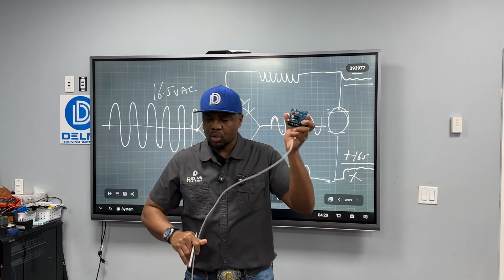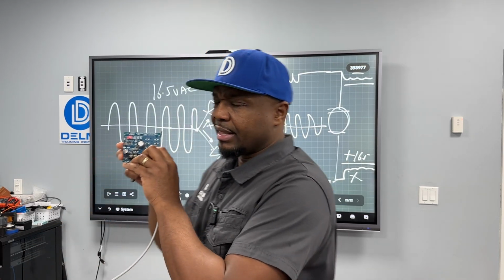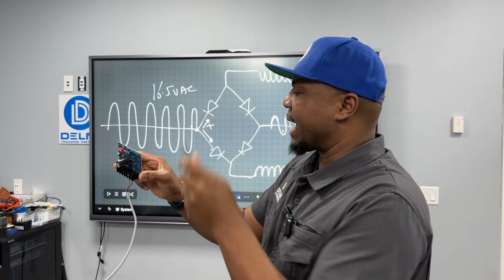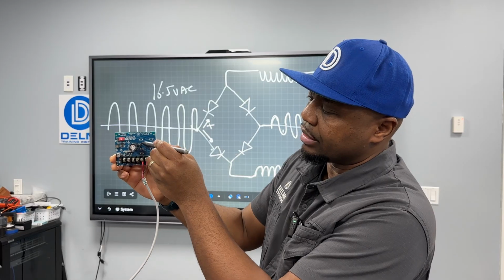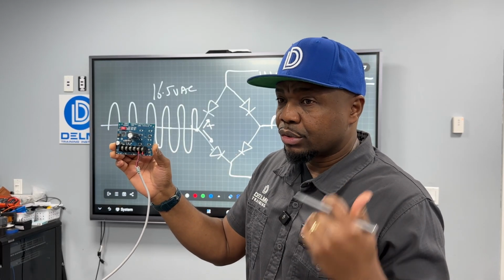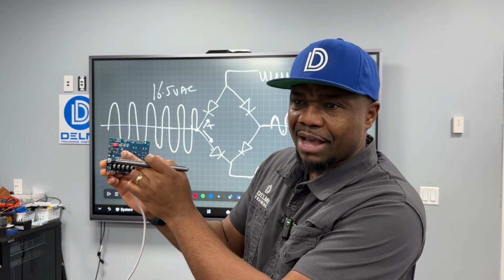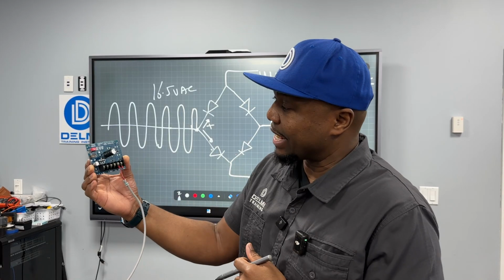So when we look closely on this electronic board, you'd notice one thing here. We have the diodes on this component. So this is 1, 2, 3, 4. They have those 4 diodes that are going to do the rectification. And obviously we have a capacitor in here. And this capacitor is what is going to do the filtration and also provide an active source.